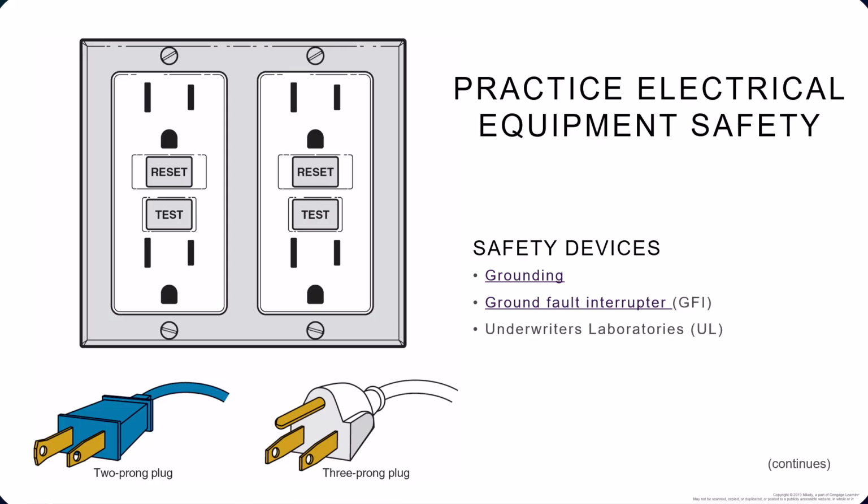For extra protection, some appliances, especially the bigger ones, are going to have a third circular electric connection called a grounding pin. So it's called a 3-prong plug, and it's designed to guarantee a safe path for electricity and to protect the user from an electrical shock even if the wire comes loose. These offer the most protection for you and your clients. So a lot of the time you'll see those on the bigger devices that we use.